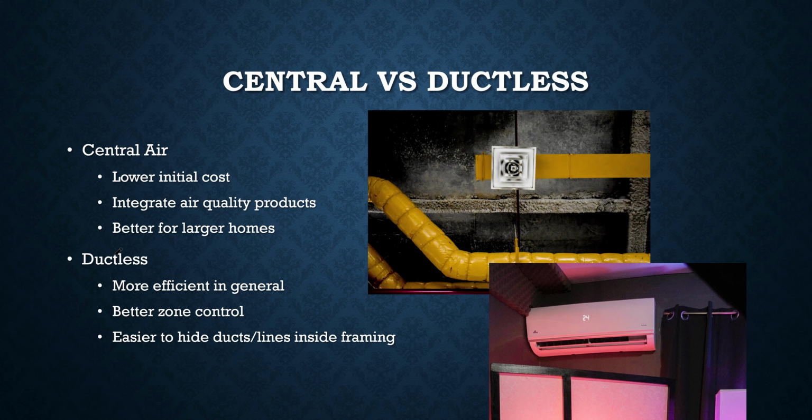And you can actually clean out all the air and have very clean air, not just nasty outside dusty air if you're next to a construction site or something, right? You can have very clean air inside your house being blown around versus a ductless where if you have a dusty room, it's going to have a filter in there, but it's ultimately just mixing the air that's in that room. It's not pulling that dust anywhere else, which is part of the reason you need to maintain ductless filters much more frequently than a central filter.